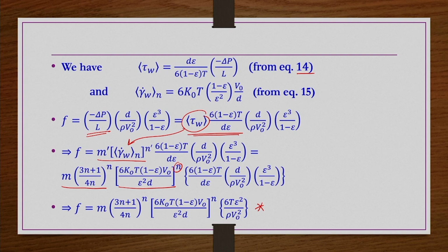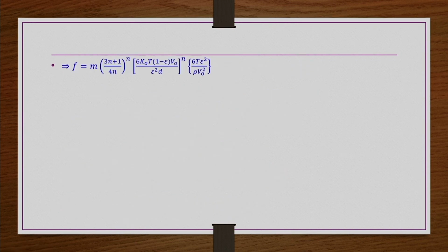Average velocity, how much average velocity you wanted to have through the bed, so all those things are known. Fluid rheology is also known a priori. So then the friction factor you can calculate using these relations. If the friction factor is there, then the pressure drop you can find out. Okay. So, the same equation rewritten here.